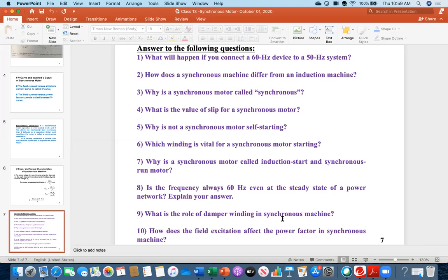So that is the meaning: in a synchronous machine, you have to take into account that it covers both generator and motor. Accordingly, you have to answer. So that is the perfect answer: for a synchronous motor, damper winding is needed to initially start the motor, and for a synchronous generator, damper winding is needed to eliminate hunting. Yes.